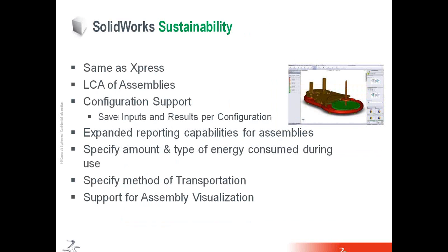And the second product is called SolidWorks Sustainability. It is a full blown out product from SolidWorks, and the functionalities or the capabilities are same as Express, but apart from that, you can also do the lifecycle analysis of assemblies. It also supports configuration. So let's say if you have 3 or 4 configurations in your assemblies or parts, you can save different set of inputs and outputs for each configuration. Also, it has some expanded reporting capabilities for assemblies.